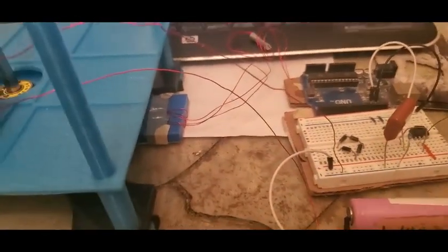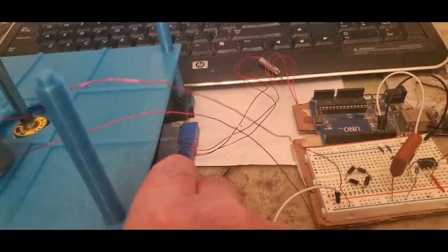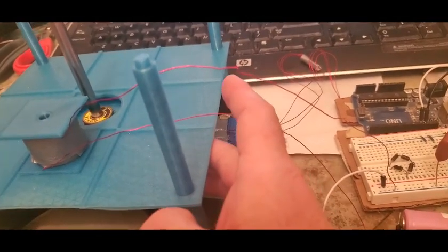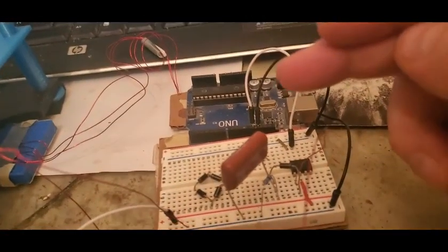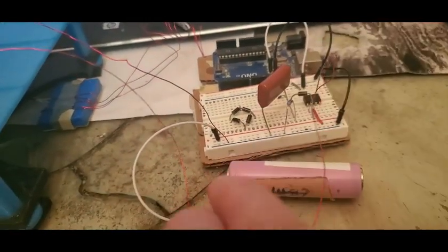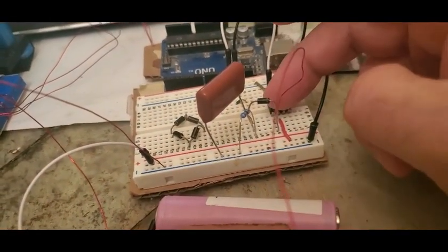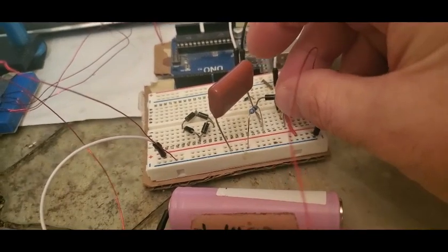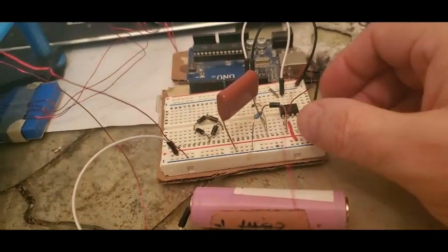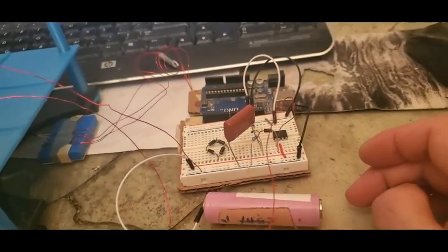So let's just talk through this circuit for a brief moment. You have your Hall effect sensor, which is telling you whether it sees a magnet near it. If it sees a magnet near it, it tells switch 13 to close this switch. When that switch closes, power flows from the positive here through the red line across the switch to one end of your coil, around the coil to the ground, which is where this black one is. So if I connect the black line to there, the thing should spin.